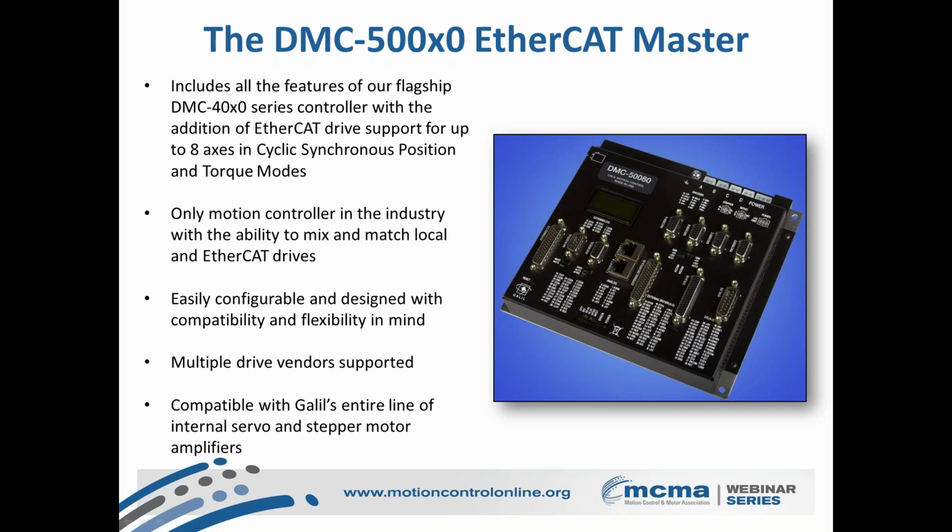So with the EtherCAT network, typically that coordination takes quite a bit of effort on the side of the EtherCAT master, in terms of setting up the timing, setting up the individual packets that need to be sent back and forth, and interpreting them. There's quite a bit of preamble that needs to be done, and this can be done through a number of software packages by the user. However, those can take quite a bit of working knowledge of how EtherCAT works, certainly beyond the scope of the broad range of this webinar.